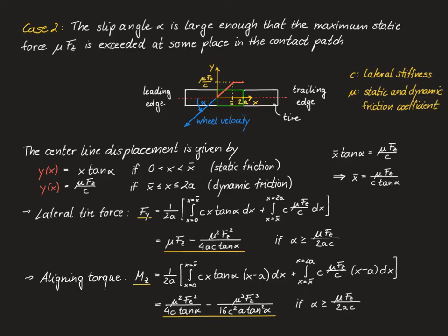In the most extreme case, so for professional vehicle simulation packages, analytical tire models consist of finite element models, so they contain up to thousands or even millions of states, just to provide a realistic description of the tire road contact.